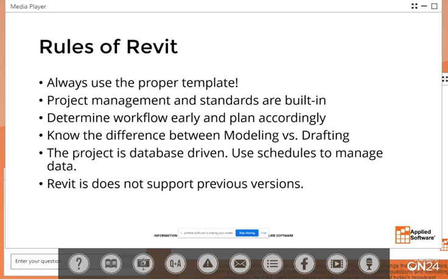So keep that in mind when we're working with Revit and developing anything from scratch, or developing your standards: you want to do it in the oldest version possible. With Revit, you get a license for 3 versions. So right now, recommended is 2021. 2020 is okay, 2021 is probably better. But create anything or develop your standards, your templates, anything custom in that version, and then upgrade it as you need. 2022, 2023, you might have to manage a couple of versions, but we'll get into that here as well, as far as best practices that come along with getting ready and getting involved in a Revit project.